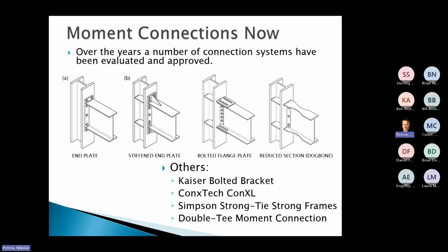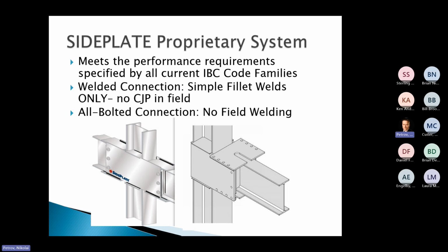I think this was the industry's first response to, we want a plastic hinge here. We're going to make it happen by literally cutting the beam. This is going to work until we can find something better. But that is a segue. Let's move into side plate.